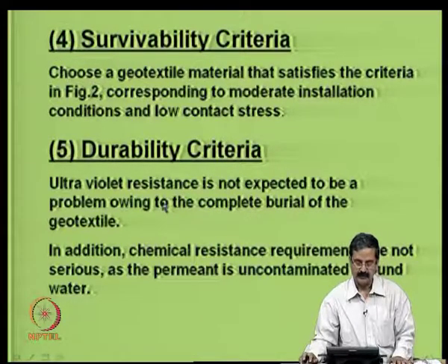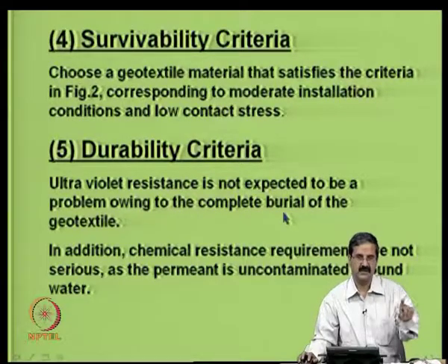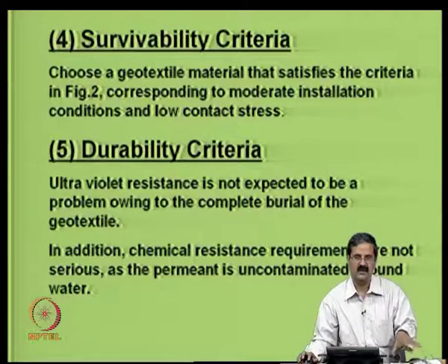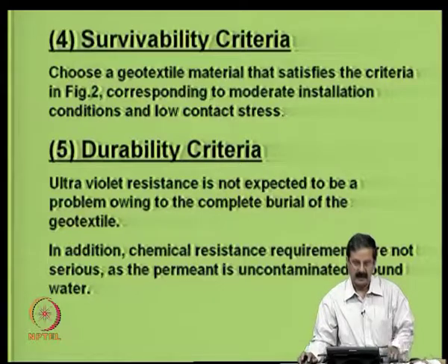Since we are placing this geotextile beneath the gravel cover, you are burying it. So, exposure to sunlight or ultraviolet resistance is not an issue at all. So, there is no problem.